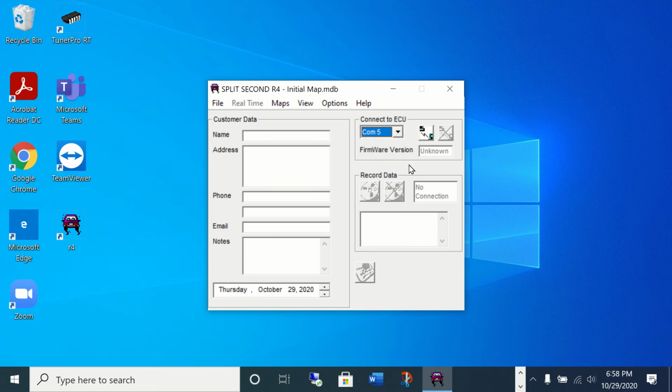So now, if you haven't plugged in the other end of the cable, great, you can plug it in now. But the key is plug in the USB side before it sees activity. Once the AIC1 is turned on, it's going to start talking. And if it's talking when you plug in the cable, it could cause conflict in communication. So the graceful way to do this is plug in the USB side first, then either plug in the other side or power up. You can have the 9-pin serial side plugged in, but the ignition off on the car. So you plug in USB, then turn on the ignition.